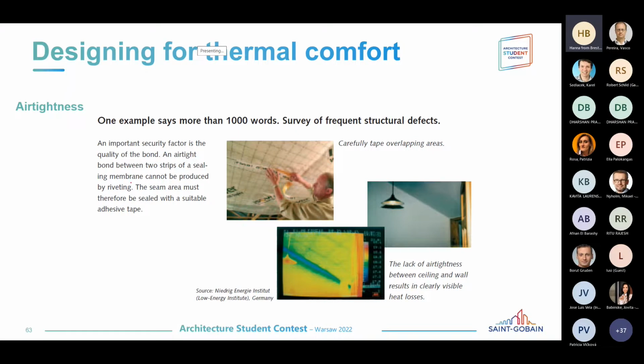Then this airtightness is easy to treat. You can, as you saw very well, visualize it with the support of some thermographic camera and with the blower door test. This blower door test is today something that is very common and, as mentioned, required in many countries. And once you have planned it from the design stage, when you are at the construction stage, just before covering the airtight layer, you can do these measurements.